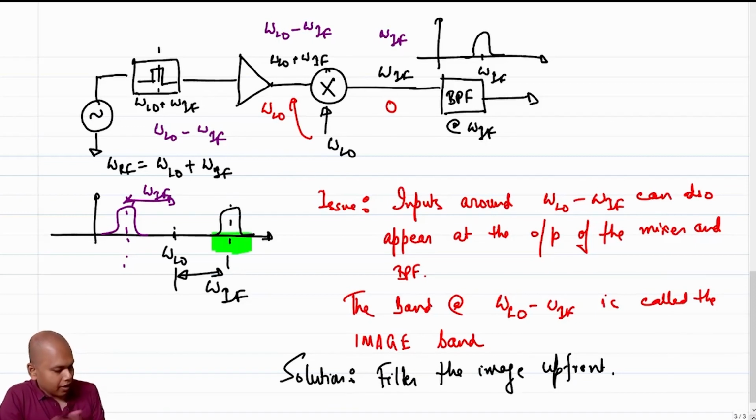Okay. Now at times the interferer that comes in, your SAW filter will never be able to fully reject anything, right? It is going to only suppress. Now depending upon the specs of the band, if the SAW filter, let's say, is able to reject up to 40 dB, and you want another 40 dB rejection or another 20 dB rejection, then you might have to put a separate filter on chip, right? And that is often called an image reject filter, and that is surprisingly quite common, right?